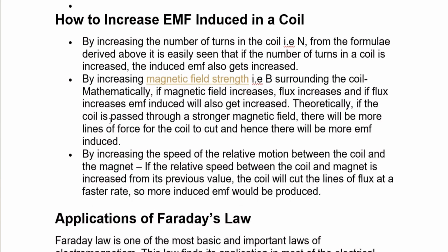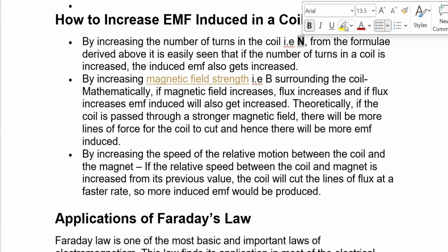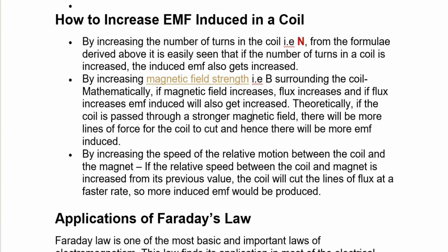How to increase the EMF? Now, this is a small quantity of EMF that I have explained. But if you want to produce a huge amount of EMF, just as you do in the case of alternators, or in the case of transformers, what needs to be done? Basically, by increasing the number of turns, you have to keep in mind, this is a thing that increases the EMF.